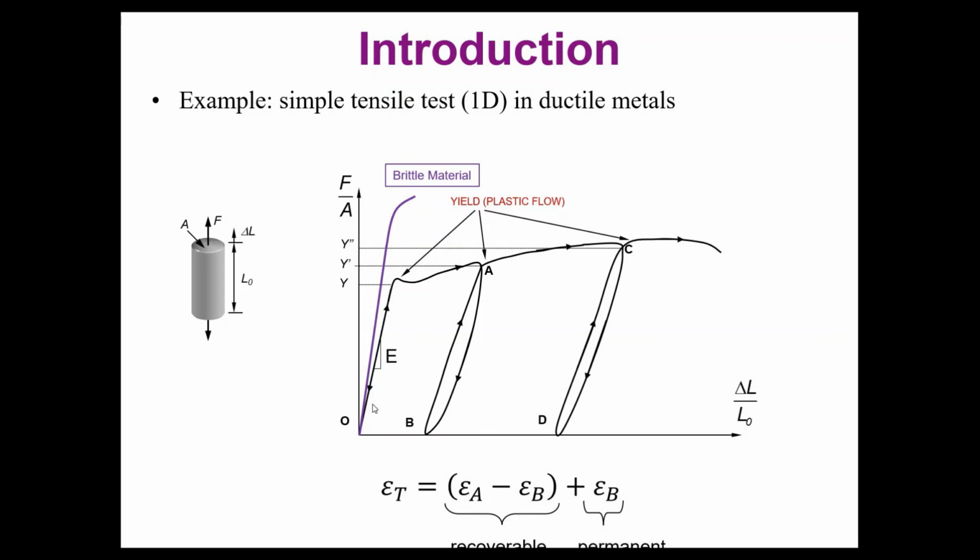In this unidimensional experiment, you see that there is only the Young modulus as a parameter shown in the figure. There is no Poisson ratio here. And this is because the Poisson ratio plays a role once you go to a two-dimensional space or a three-dimensional space. Because remember that the Poisson ratio is the relationship between the strains in two perpendicular directions.